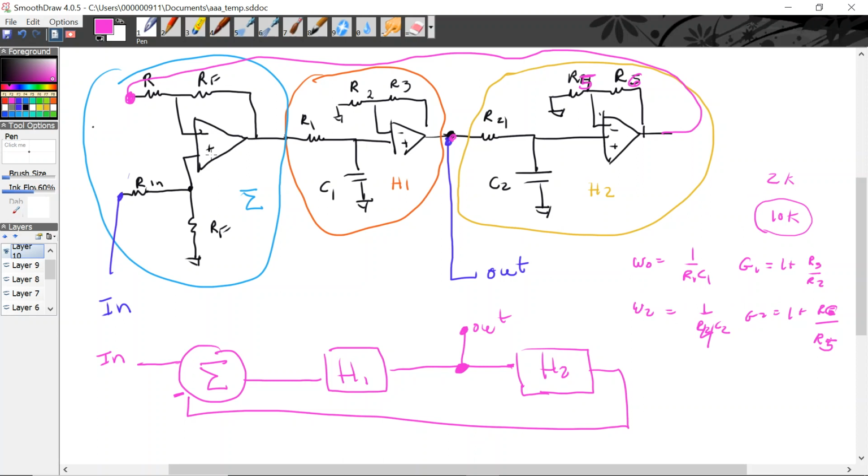And so you have an R1 and a C1. How do you choose? What you do is you choose a C1 first, and then calculate what the R1 should be, and make sure that it's not too big, not over a meg, and not too small, not less than 2K.